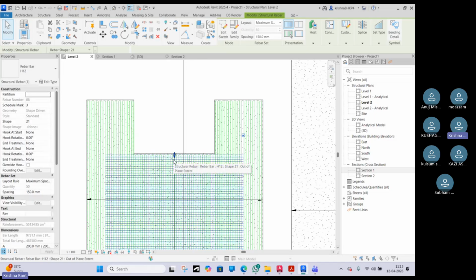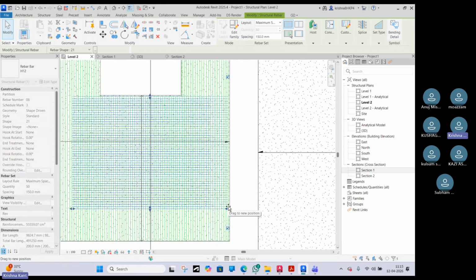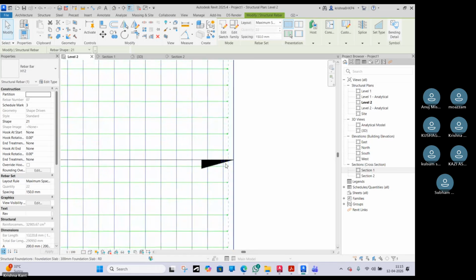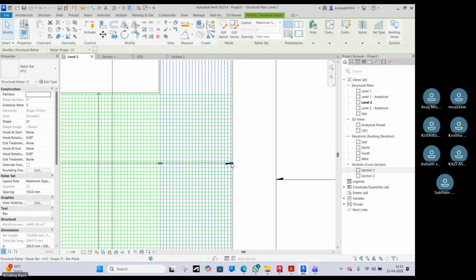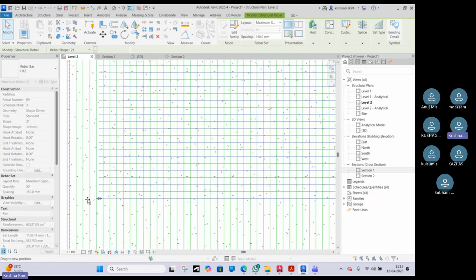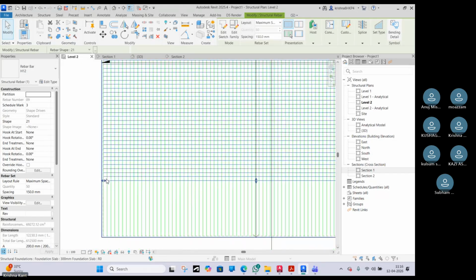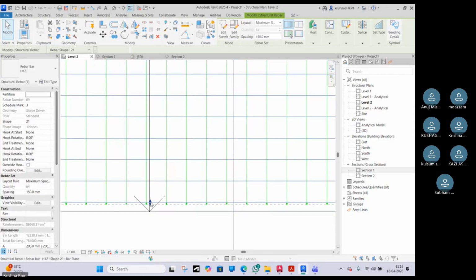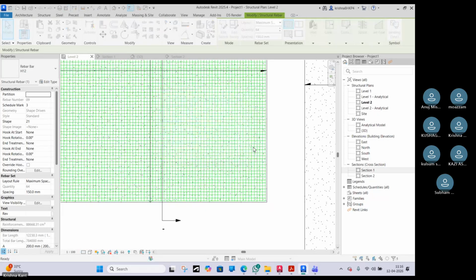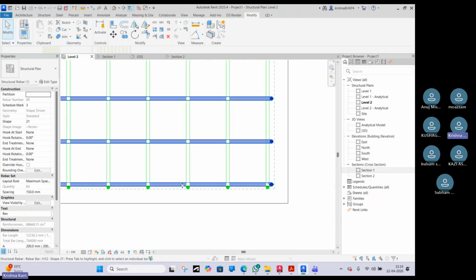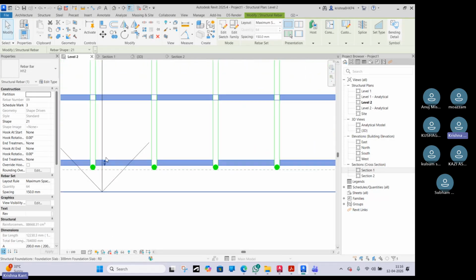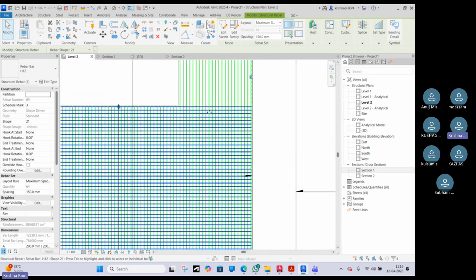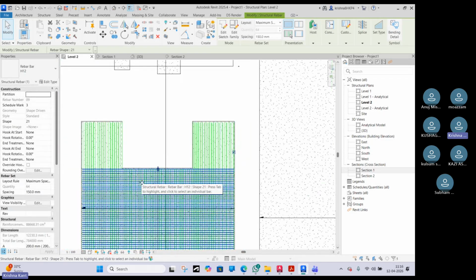And this direction bar, I'll pull it over here till this end of cover. Pull this one till this ending. Okay. Fine. You will see the actual rebar whether it is clashing or not. So if you turn on the fine detailing, that will be very much fine. Okay, now from this end to here, we can't provide it like this.